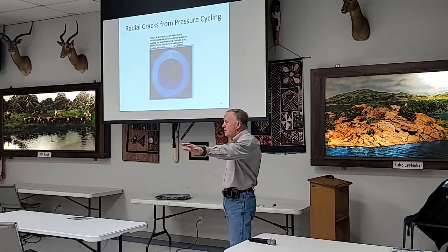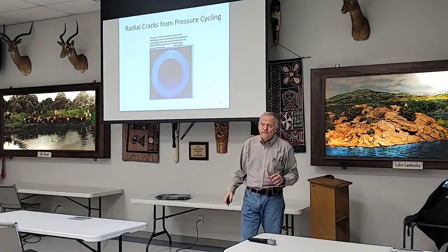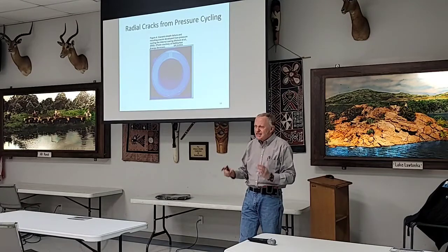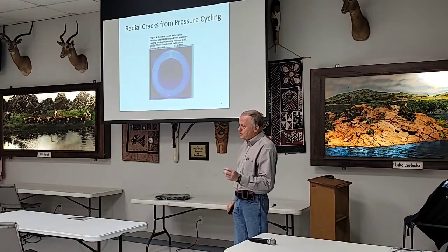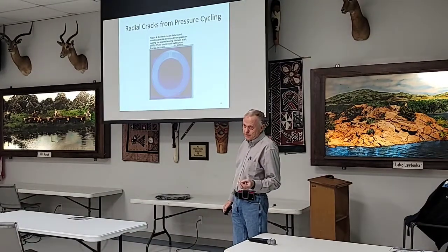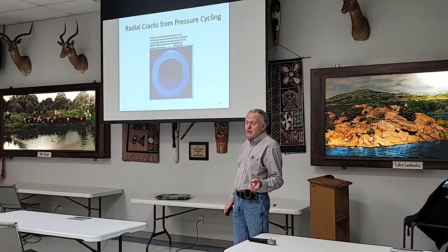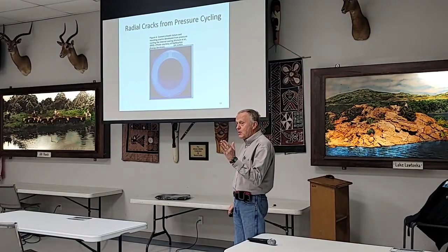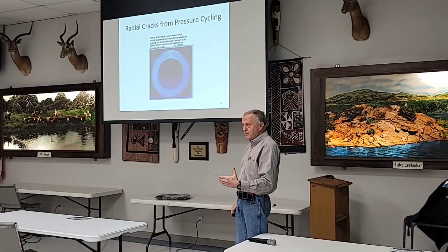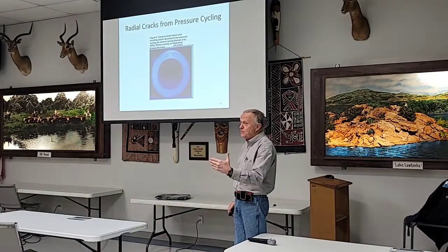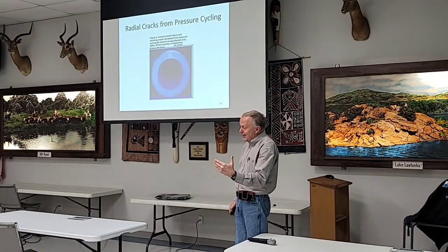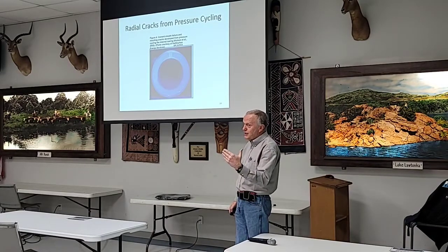If you have an area that is specifically very, very susceptible to this, consider that cement, put a little latex in there, use a harder cement, a stronger cement. But after a while, no matter what you're doing, you're going to destroy it and get your microannulus in there. All right, that can be cured by the formation. I'd hate to count on that as my only cover.